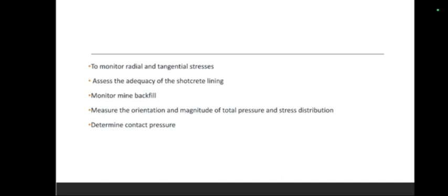The vibrating wire pressure cells are much more reliable and faster than all other types, as they are capable of taking readings electrically and the frequency output is almost immune to external noise. The cable from the pressure sensor is connected to the readout unit or data logger and is protected against any possible damage during construction to give all around reliable data.